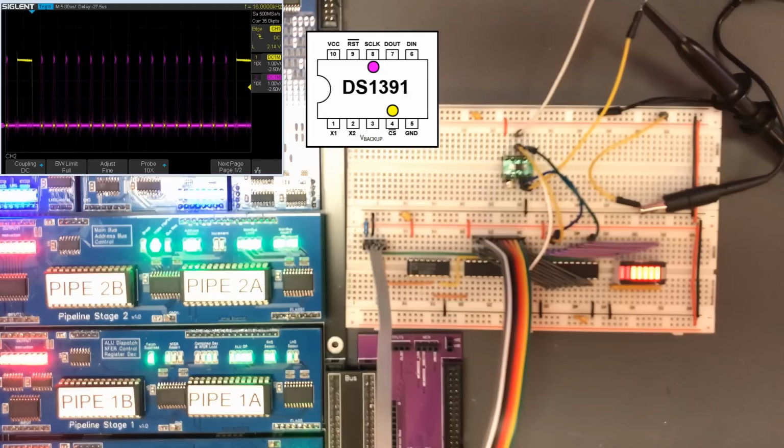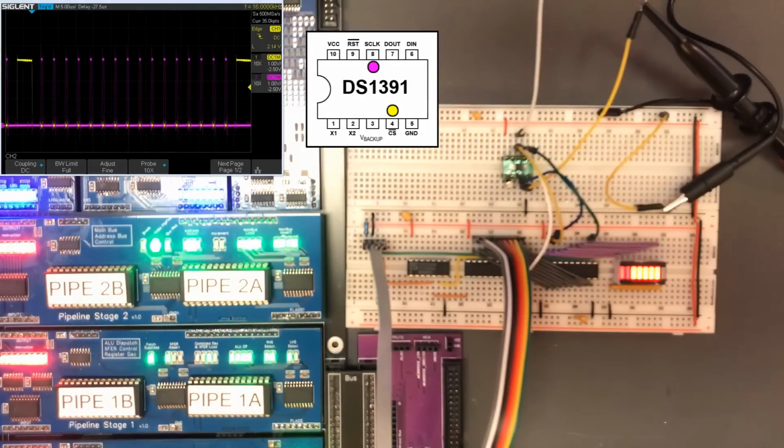Okay, one thing that's immediately apparent is our clock line spends a lot more time low than it does high. Now that's going to be because we've got quite a short number of instructions between setting it high and setting it low, but let's move the purple line and look at data out, because in theory what we're doing here is writing a 0 to the address, which means we're reading from address 0, so we should actually be seeing data coming back.